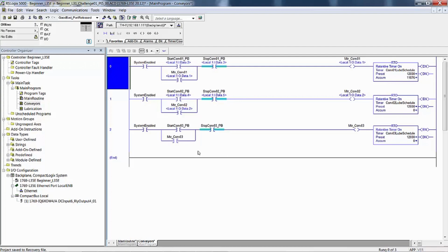Now remember, in the manual we're talking about 2 rungs. Here we're talking about 3 rungs, because I never deleted motor conveyor 3, because you will eventually add it back in and alias it to something. Now we could have cut and pasted those 2 rungs, but this sequence is much safer, just in case you have an accident with your mouse on the way to paste them. If you cut them and then never actually paste them, you could lose them. This leaves the main routine with 1 rung of logic to enable the system.